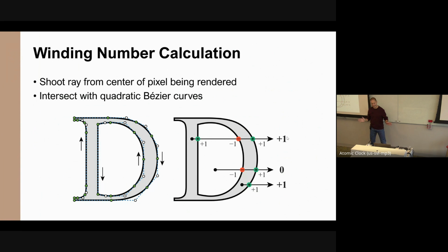So it's a simple combination, kind of think of it as a weighted average of these 3 points, where the weights change as you go from the first point to the last point, and it just sort of traces out a curve, and the shape is determined by this center control point off the curve there. And if you want a straight line, you just put those points in a straight line. Normally, you would take the middle control point and make it coincident with one of the endpoints, and you'll get a straight line.